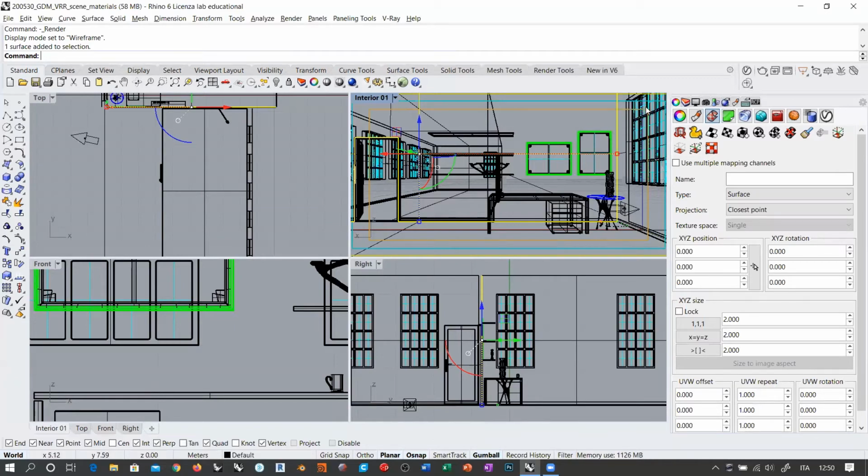So remember that when you have direct light hitting a surface, primary bounces or primary global illumination rays start from this surface. Then light can go bouncing around as many times as we want, as secondary rays like brute force, but their intensity is way lower than the primary rays.